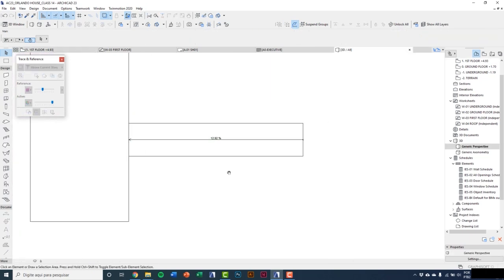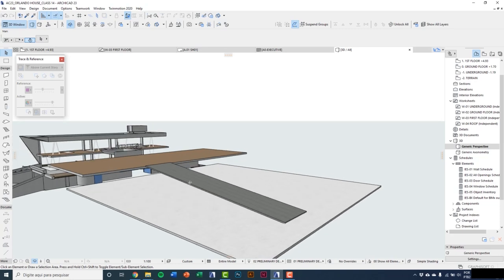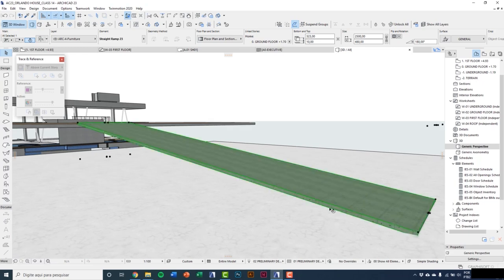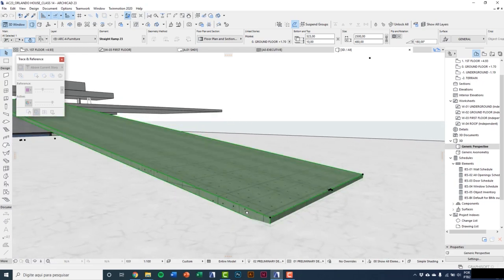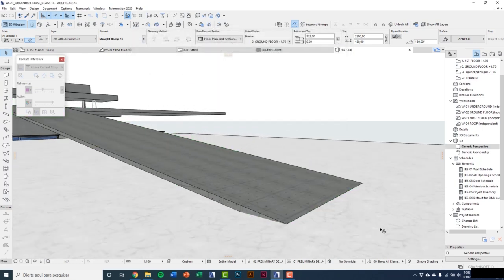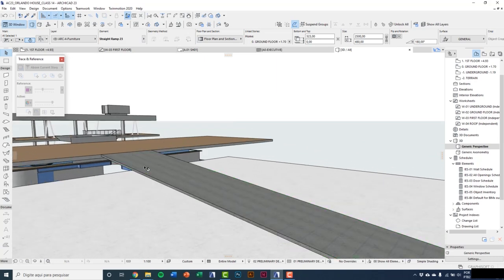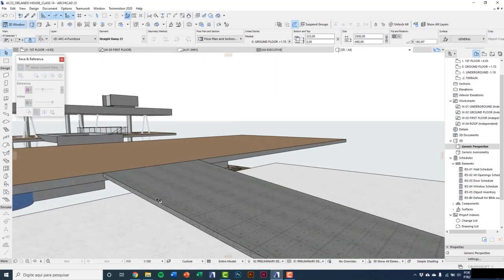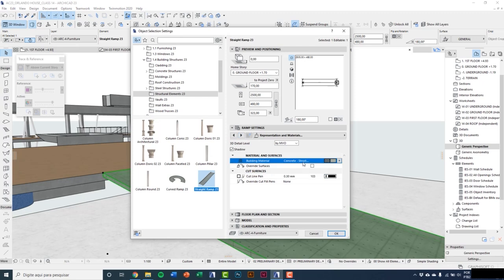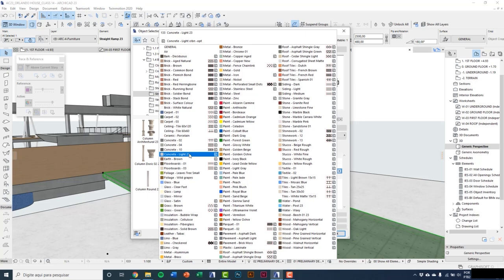Checking on 3D, you realize a difference here at the top and at the start. And it is because the level on current story is 10 and it needs to be 0. So now it's right. The surface material is the building material, concrete structure. You can override surface. It is using this material. I can click override surfaces and I'll put concrete light.